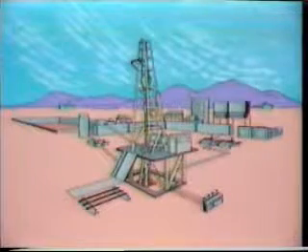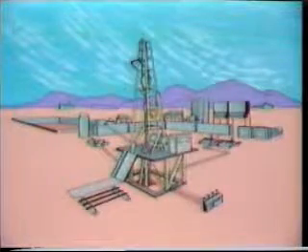The drilling mud travels through the circulating system as shown on this diagram. Mud is mixed at a mixing hopper from a base fluid, typically water, and the bulk materials stored on the location. From here, the mud goes to the suction pit, often a metal tank, where it is picked up by the mud pumps to begin its circuit. The pumps move the mud up the standpipe, through the rotary hose, and into the drill string via the swivel. It travels down the inside of the drill pipe and out through the bit nozzles into the drilled hole. There it picks up the drilled cuttings and begins its return journey up the annulus.